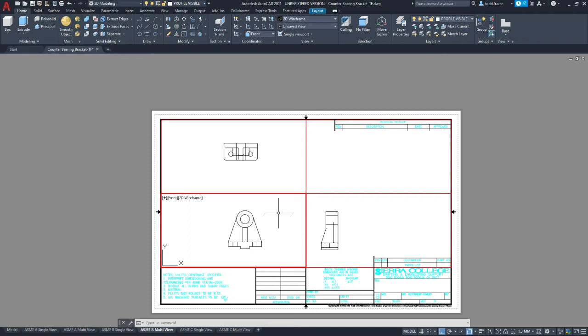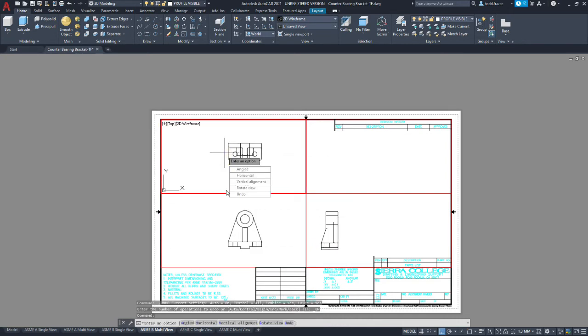Now 28, to do the alignment, there's a typed in command. Apparently there's not an icon for it. So you have to type in mv setup. Okay. And we're going to have options here. We're going to use align, and we're going to first align vertically between the left edge of the front view and the left edge of the top view.